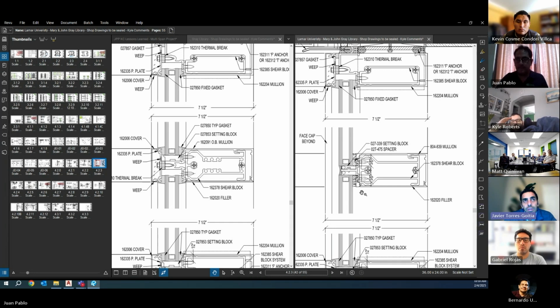So the edge of the slab, the pour stop, might only allow for a given height of a wind load clip, and if that's a limitation, there are other options like welding to the underside of the slab. In that case you can put an angle flipped on its side with a long leg attaching to the mullion. There are other alternatives to get around that, but that's something to consider too.